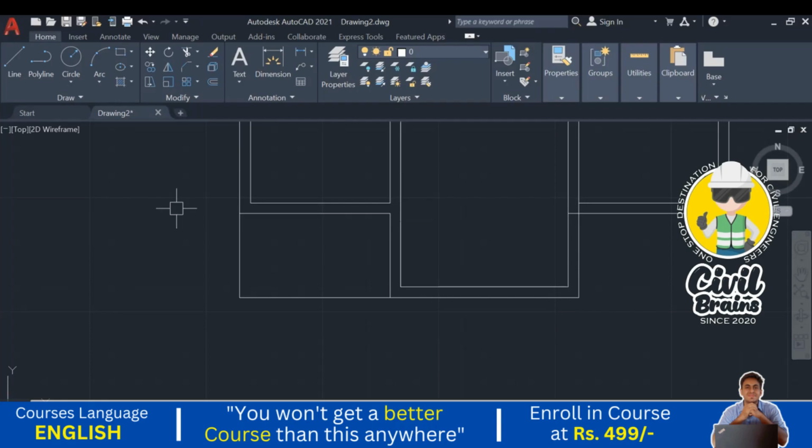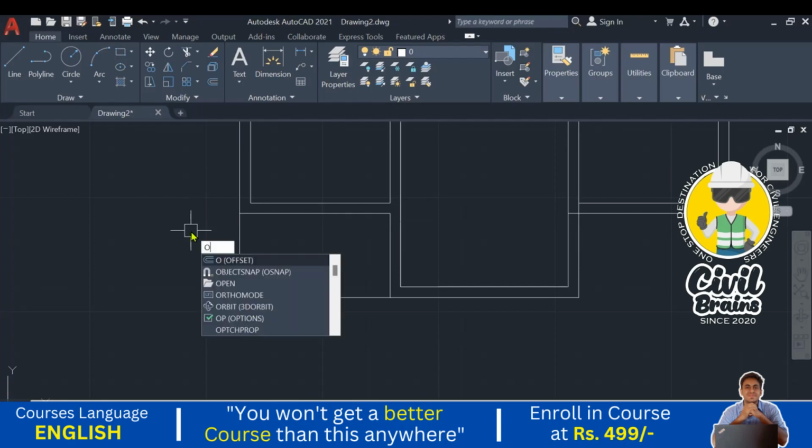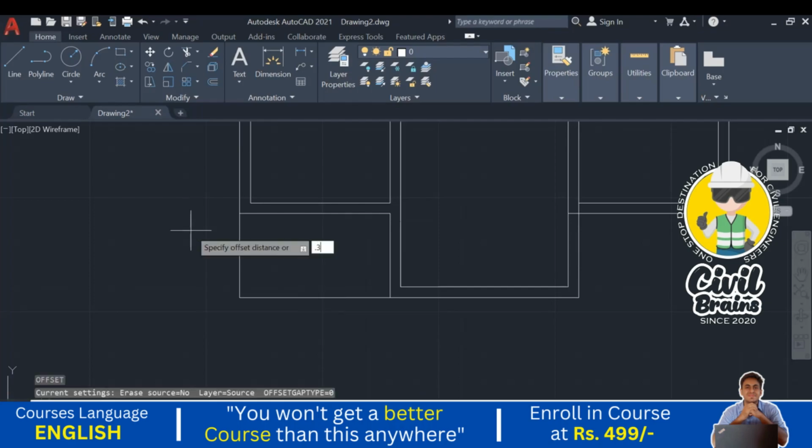It is the standard one. Tread is 300 mm, and for the riser 150 mm, so that people of any age can climb the steps easily. So offset 300. Okay, 0.3. Press enter. 1, 2, and 3 steps are there.